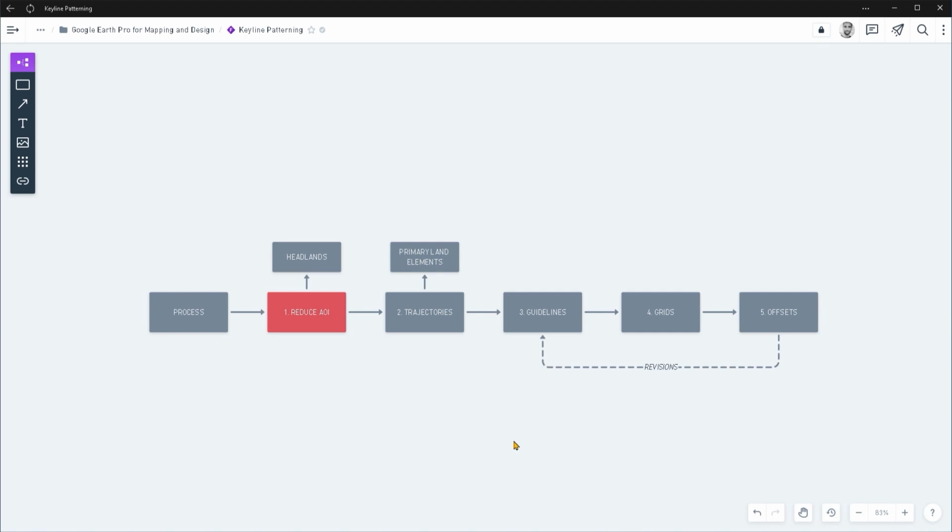What the headland width is going to be will depend on your particular context or the context of the project. Normally, this is going to factor in the width of the largest equipment that is going to be navigating this site. So if this is a tractor, then that is the largest equipment. Just make sure to also factor in any implements that are being dragged by the tractor. This could also be a wheelbarrow, or it could also be just a person.